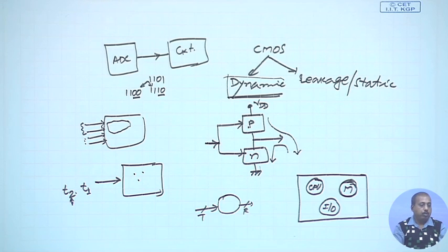Okay. So, each vendor has given me a large set of test patterns, and if I test these individual cores one after the other, it will take a lot of time. So, we try to do parallel testing. We test a number of cores together, but as a result, in normal operation maybe those cores are not going to act together.